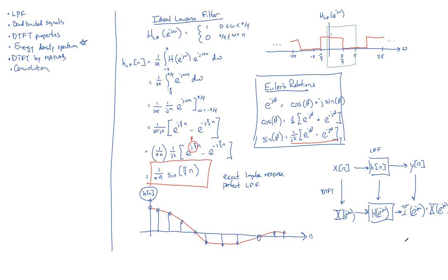So we're just talking about the system here, the thing that changes our signals, and then you can plug into it whatever you want. This, by the way, is also the way that the filters would be designed in any kind of music listening system, because now you can change your filter and make it more bass heavy, less bass heavy, dynamically. Just simply recompute the new h of n, plug it into your filter, and then inside your MP3 player, there's a convolutional operator that's continuously convolving this with your input x of n to give you your output that you're listening to. It's doing it in real time.